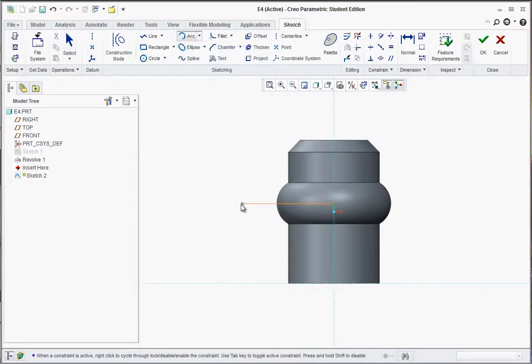Glide up to that vertex on the far left, click and drag it straight to the left and then up. And you'll see a little T appear for tangent. You don't want to make this a straight 90, just make it a little bit less. See where it's snapping to the center point? So just a little bit less than that. You don't want to snap it to the center point.